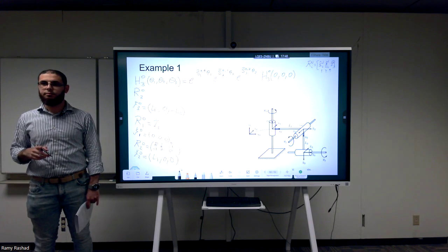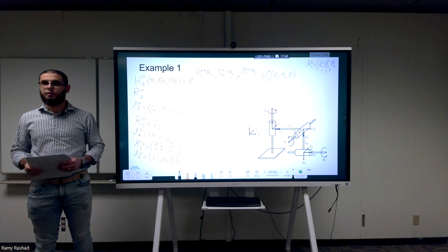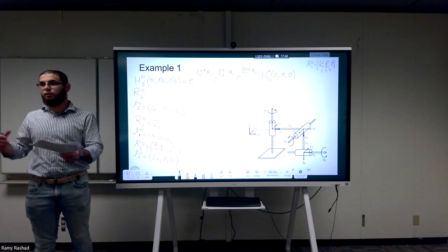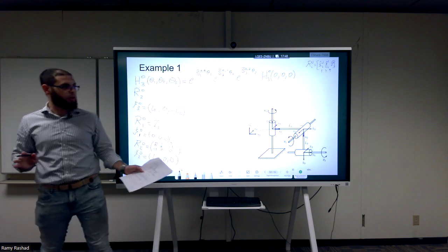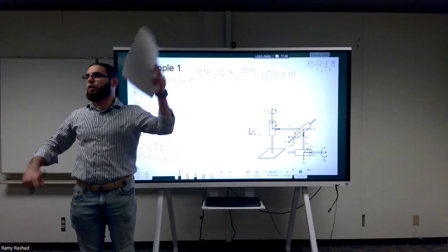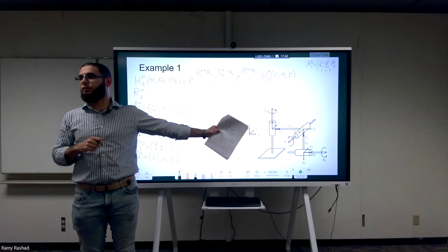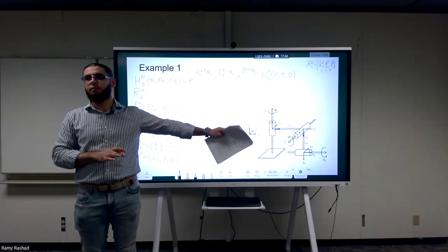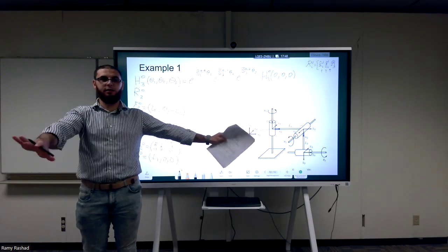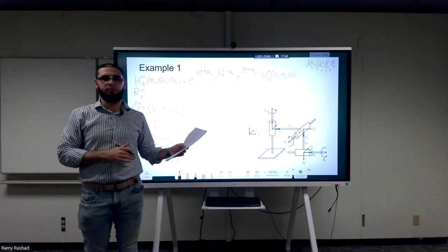The theta component into the rotation. You mean because we're going to be rotating, right? Very good point. Excellent point. Theta will start moving around, right? Do we care? This is the power of the product of exponentials formula. We do everything in the home configuration. That's it. And you plug it into the product of exponential formula, it will calculate everything for you.